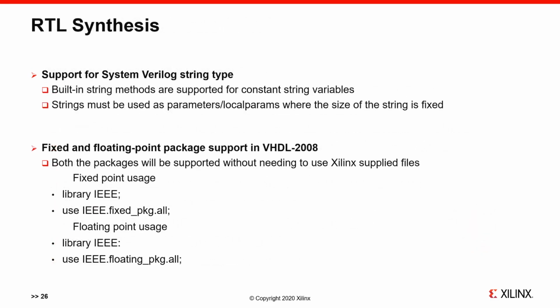Under the RTL synthesis section with 2020.2, we are adding string support for SystemVerilog. Built-in string methods are supported for constant string variables. There are a couple of rules to be aware of though. Strings must be used as parameters or local parameters where the size of the string is fixed, and strings cannot be used in logic.